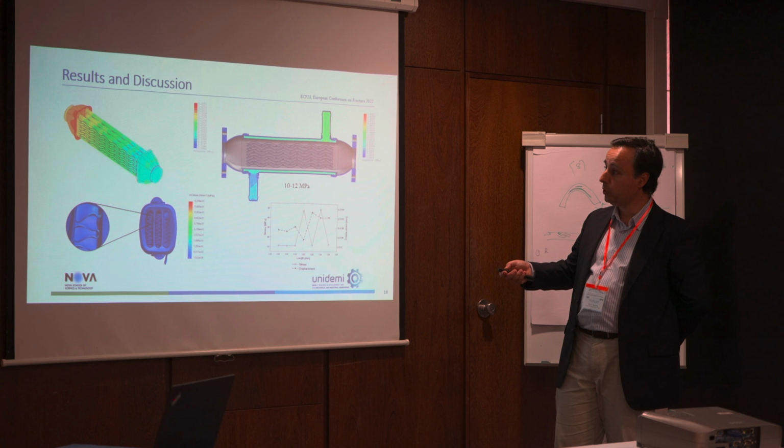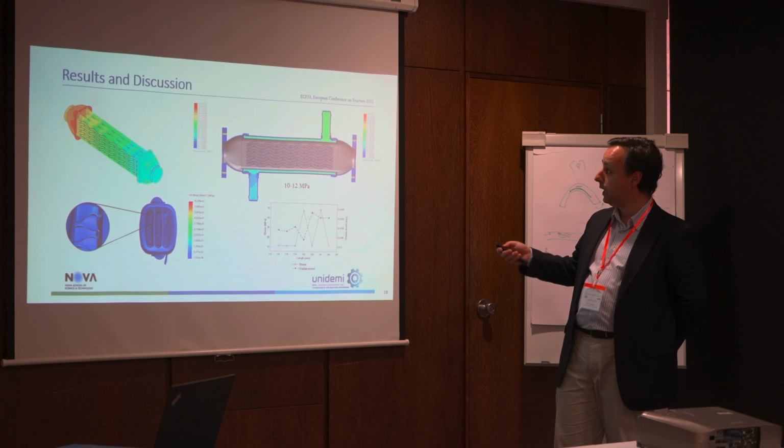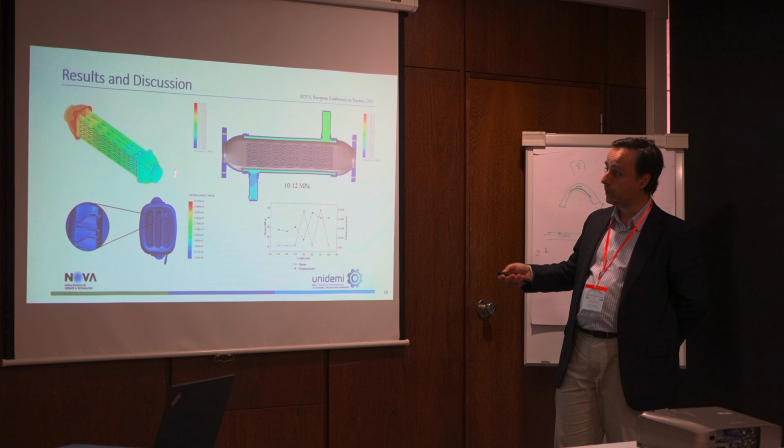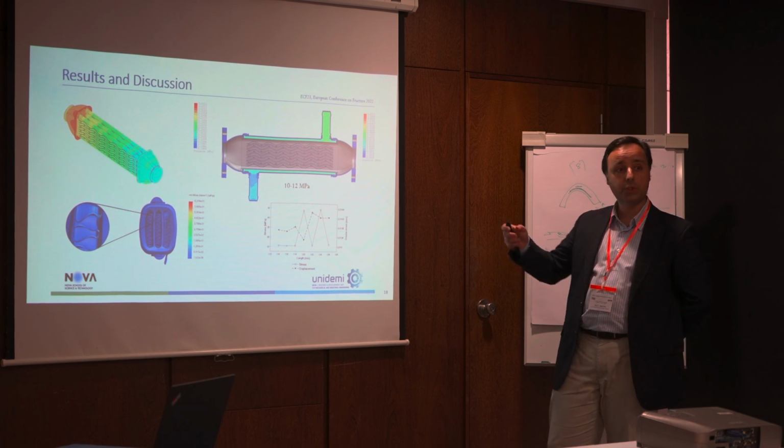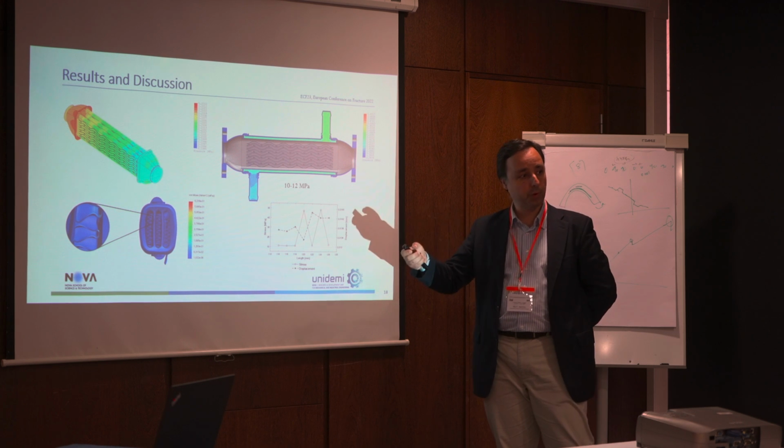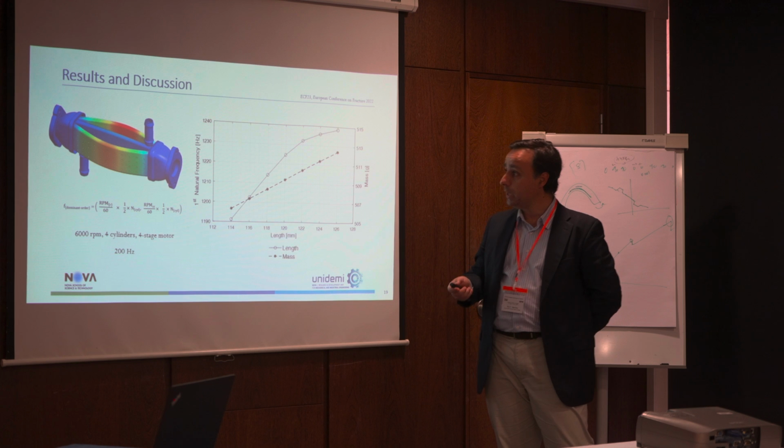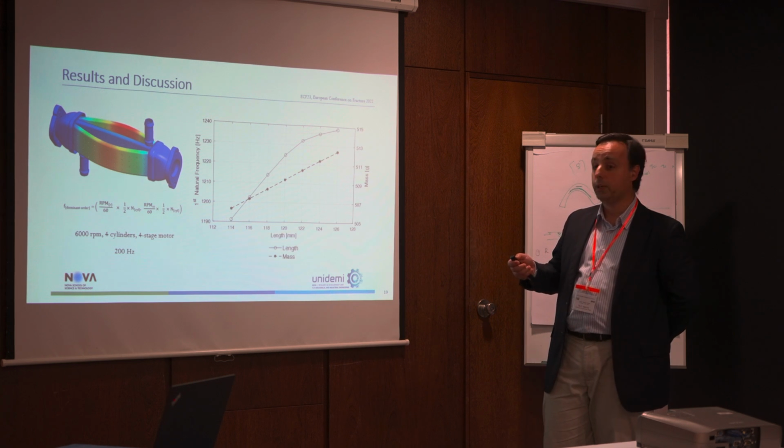Now, looking at the exhaust gases and also at the pressure exerted by the coolant, we can see that for the exhaust gases the stresses are very low, and for the coolant also the same, and the maximum stresses that are applied are in the order of 10 to 12 megapascal, which are very low when compared with the thermomechanical and the thermal stresses induced in the system. Finally, another important thing is vibrations.